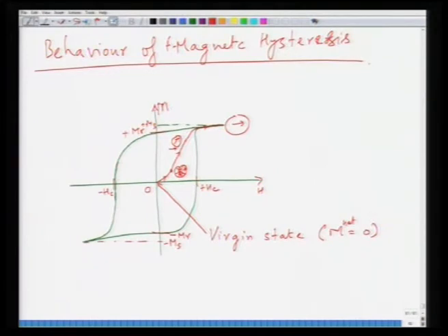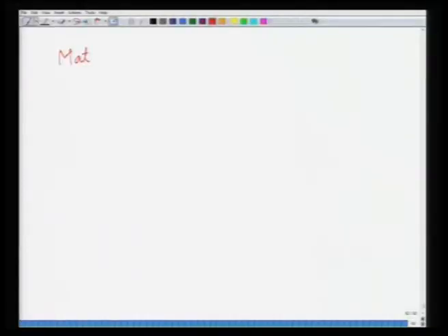Typically it is defined in terms of ease of magnetization, and this ease of magnetization essentially is about the coercive field. Typically, a large coercive field would mean that domains are not easy to switch, which means you cannot reorient the domains without applying a large field, and that is why materials with large Hc are called hard magnets.